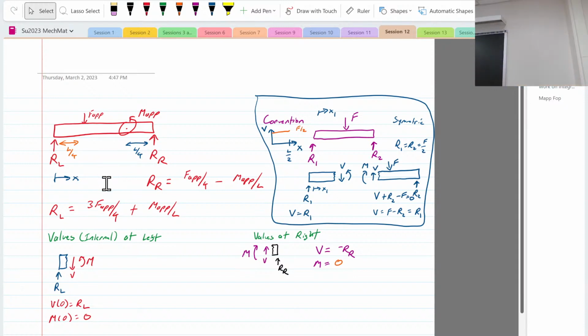It is pretty tricky, but we start off again looking at what is external equilibrium, and then looking at what's happening at the boundaries. What are the internal bending moments and what are the internal forces, shear forces, at the right and at the left, and then we can use the integral. Is the moment caused by the applied force on the right side working with or against the applied moment? They are independent external loads being applied to the beam.